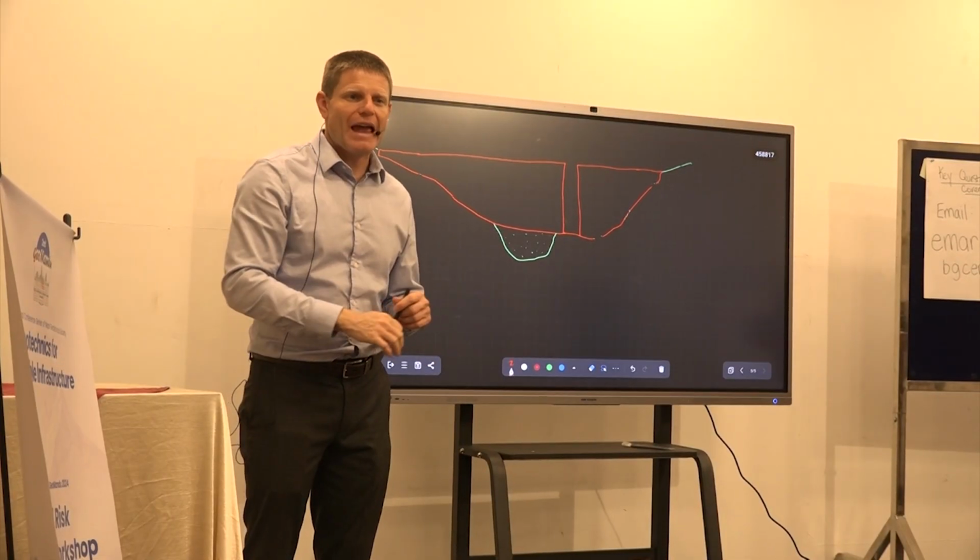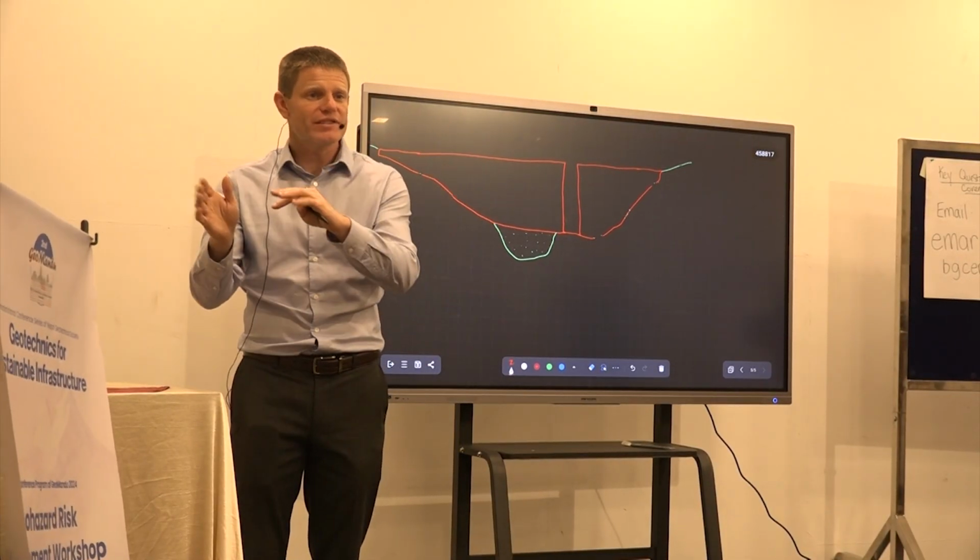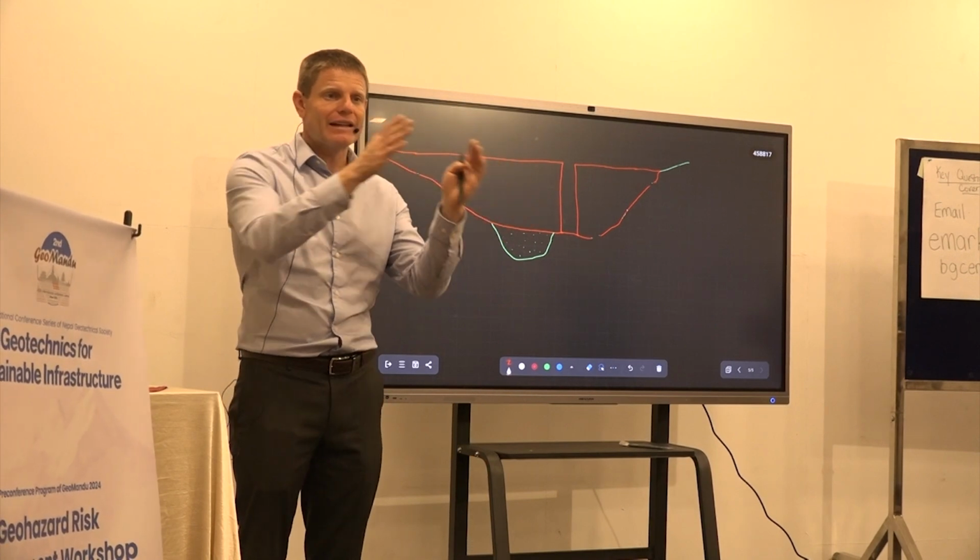Due to overturning of the dam, bearing failure, sliding failure, translational failure, upthrust, and seismic activities. And not likely components are thermal effect, fire hazard, liquefaction, and wind load. Thank you. So that was a description of failure modes, and you separated them into categories of what you felt was likely and unlikely.